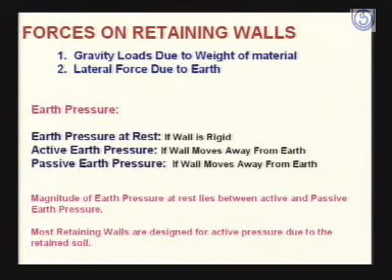And if you just think about this earth pressure, it is so heavy, so intense, that even the earth pressure at rest is so intense that under its action the wall moves slightly away from the earth or the retained material.